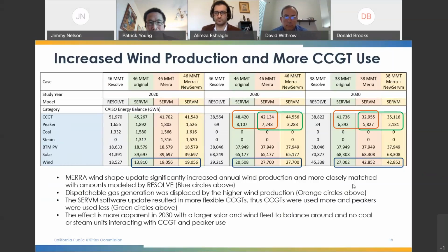When we compare the historical wind profiles that we pull from CAISO's website or other places, it looks like the minimum output in the summer for wind is in hours 12 and 13 instead. There may be some data alignment issues on our end, or if you have any documentation on how those shapes were calibrated ultimately.